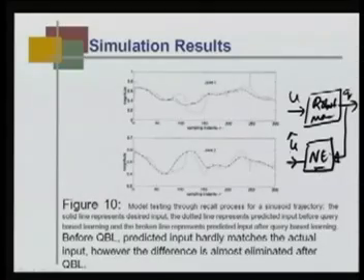Again I repeat, what is the meaning of validation through inversion? Of course, we have trained this neural emulator by giving the training set U and Q to this NE. So obviously, if I give U, it will predict Q, but given Q, can I predict the U? This is the question we are trying. If the neural emulator does a perfect job both ways, then it is a robust identifier, a robust model of the actual robot manipulator.